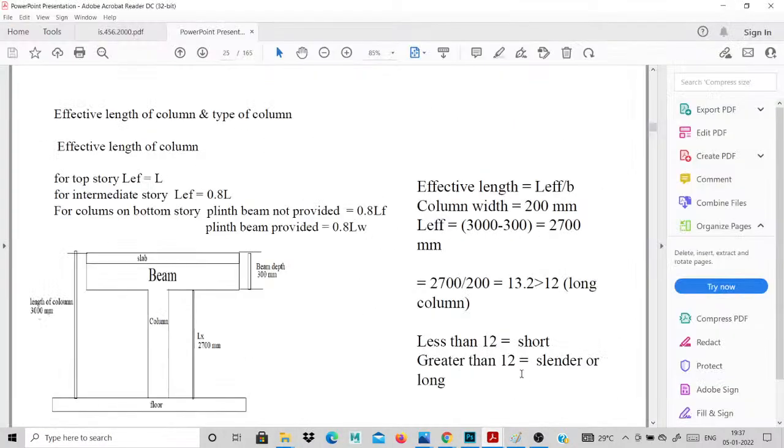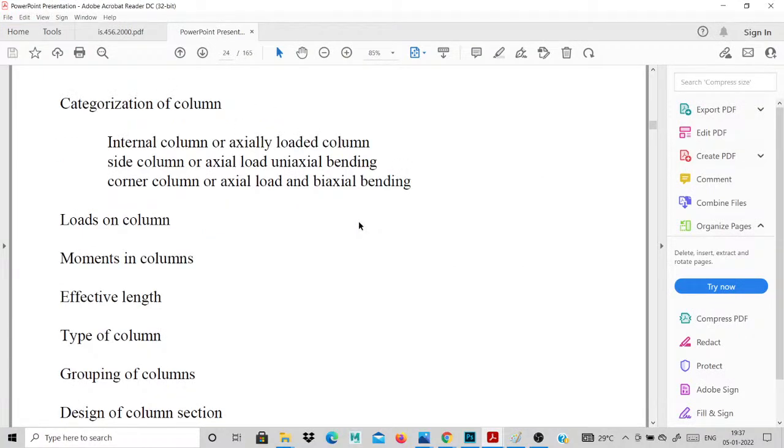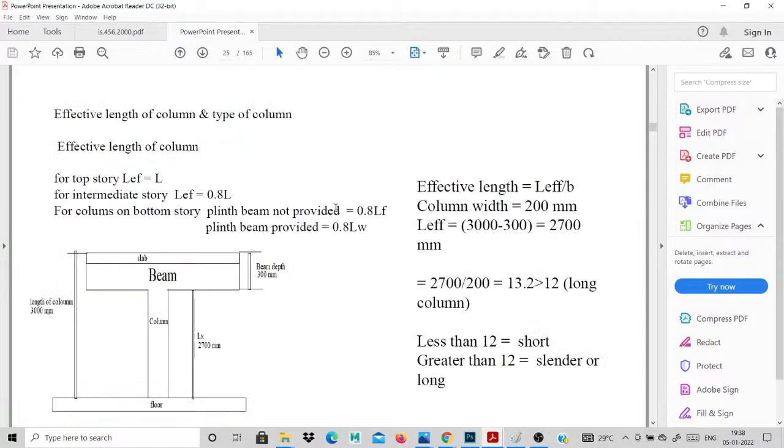This is column design, the same procedure. The next one is the eccentricity. The minimum eccentricity follows 20 mm based on your column condition, and the formula automatically provides the conditions. The next is allowable slenderness and the initial moment for braced and unbraced columns. Many types are there, and you follow this design of initial moment. You calculate the braced column and unbraced columns. This is the main concept. Then you go for the next one.